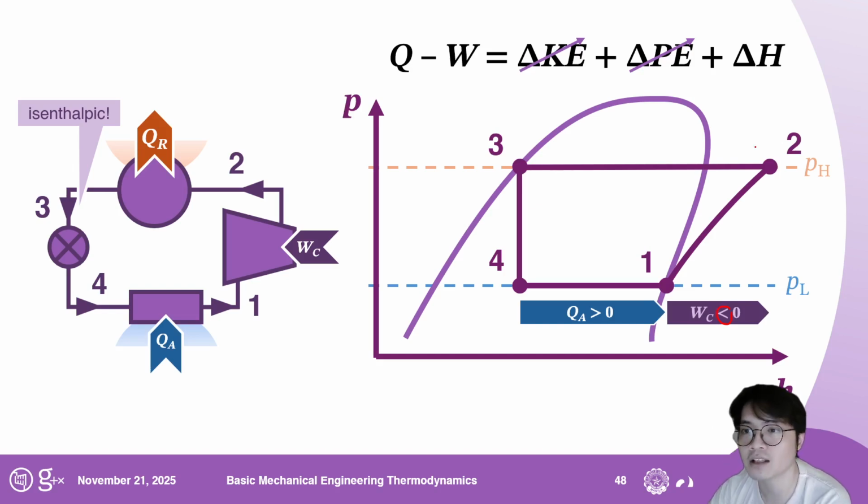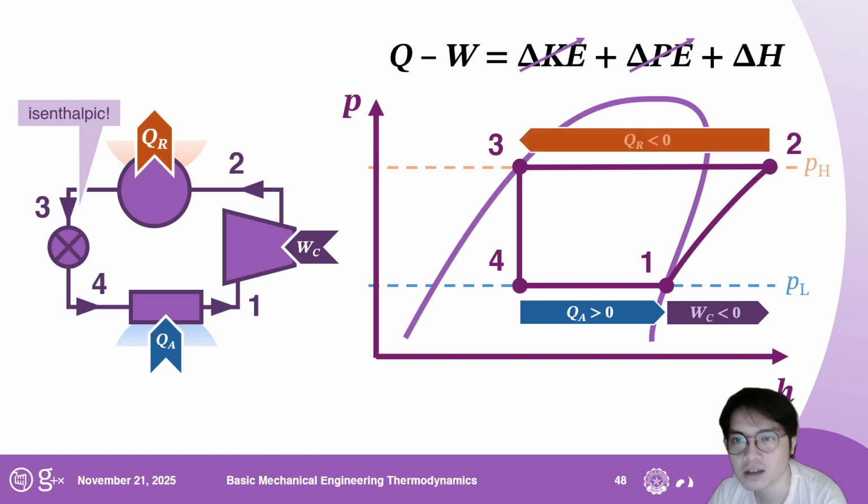What will happen now is that from state 2 to 3, you are now reading it from right to left. There's going to be a marked decrease in the energy, or in the enthalpy, of your fluid, and that is described by this length. Now notice, why did I highlight those three lengths right here?